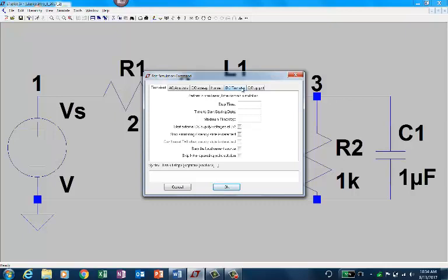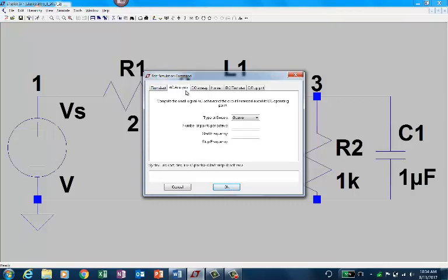You vary the input, you want to see what is the input, what is the output, the transfer relationship. And you want to see the noise, we will not do it here. But DC sweep means that you sweep a particular DC voltage from 0 to 10, you want to see the output. And then the AC analysis, basically the frequency: you vary the input with a certain voltage, with a different frequency, you want to see the output.